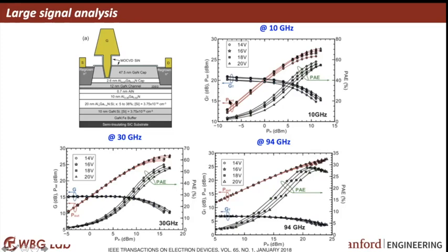This is not what I did. This is one of the results I wanted to show at different frequencies, which I took from the literature. At 10 gigahertz, this shows how it amplifies the signal. dBm is the unit we use for power. Let's say when you input 5 dBm, you get about, yeah, less than 20, so the gain is around 20, it seems. So how you get a higher output power, how you amplify the signals, we need to do this sort of characterization for these devices.